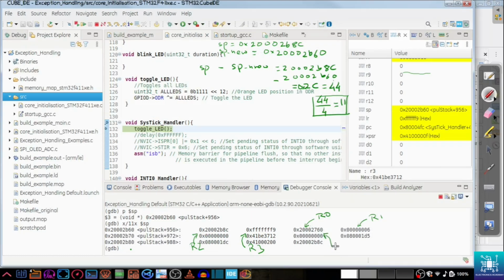So we are actually going through the stack in real time. Okay, that is the stack without floating point. So R0, R1, R2. So what comes next? R14. R12, R13, R14 was the link register. Now this is the previous link register. So when we jumped from main to this ISR, this was the link register contents. Now the link register has changed, as you can see here. This was the link register content before it jumped to the main.